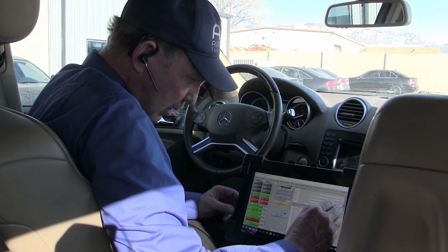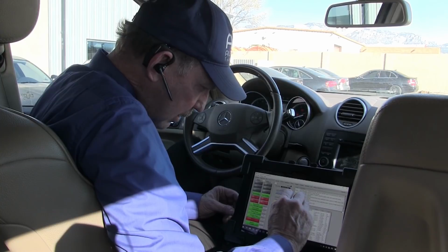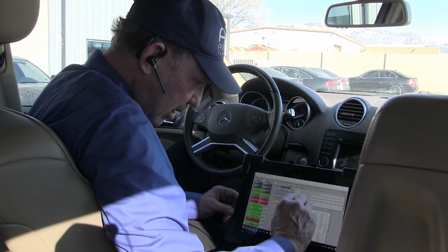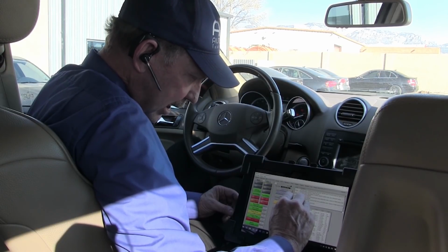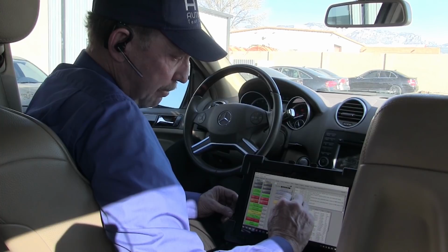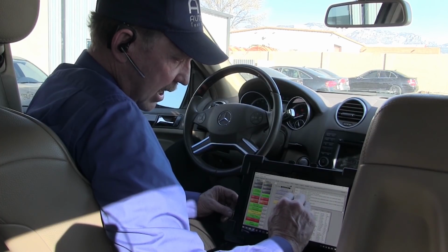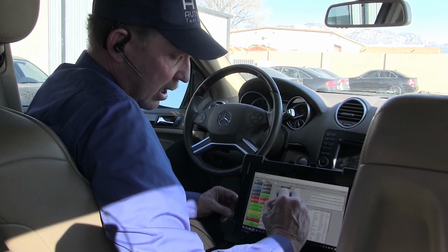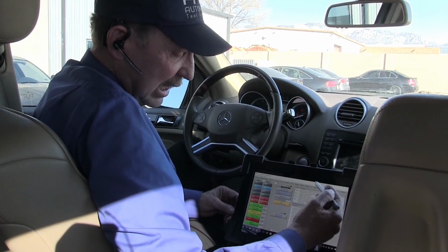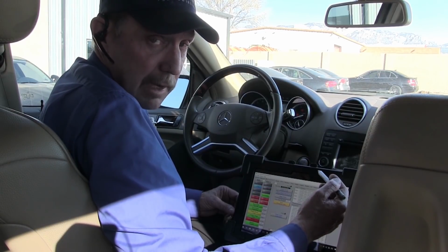And then we can see that we have codes for missing cylinders on 1 and 5, and we have an injector circuit malfunction. Now don't get caught up in a code like this, because I'm working for another shop. They might have unplugged an injector. That might not have any validity on what our codes are. So what are we doing here? We're looking for a lean condition and it's lean enough to make it miss.